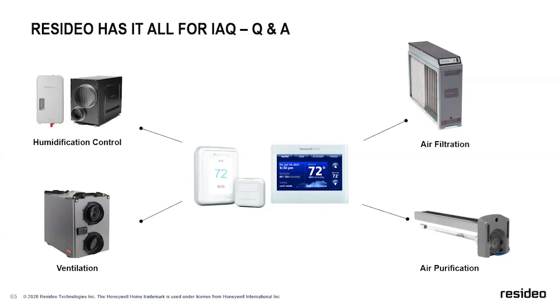There's a question on, I guess, UVCs. Do you have data sheets like RGF on virus UVC kill rates? Well, that data is actually ASHRAE data. There is a published, what they call the kill factor for all viruses and bacteria. And that's something that can be obtained through various websites. I don't think we have one per se, but we get our information just like everyone else does from websites like ASHRAE and other organizations. The World Health Organization, I believe, has that information as well.